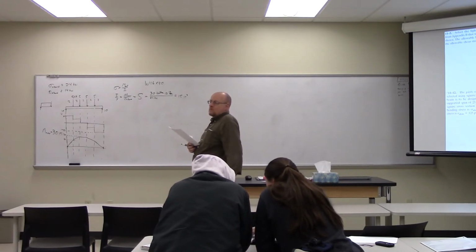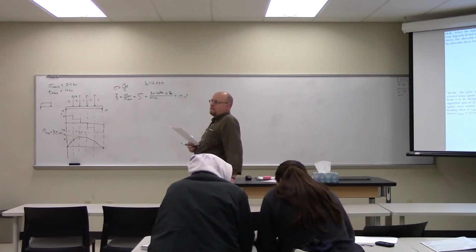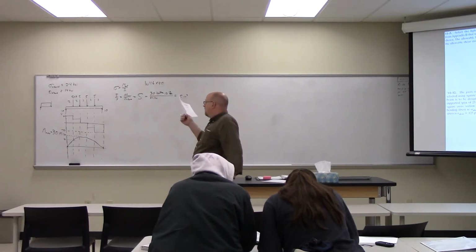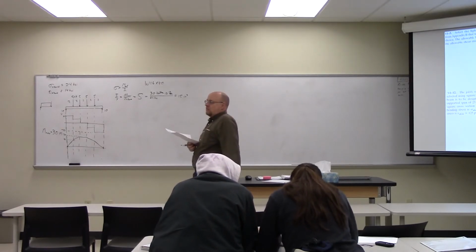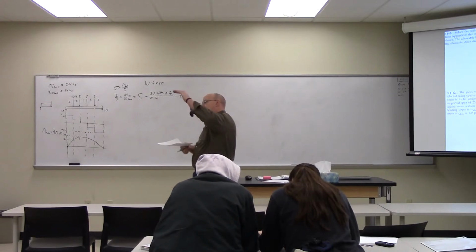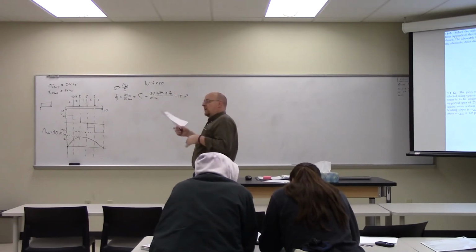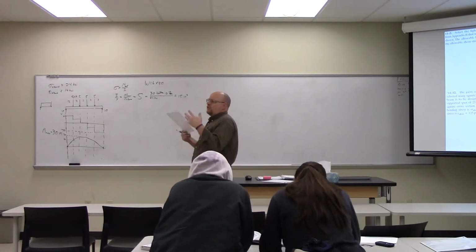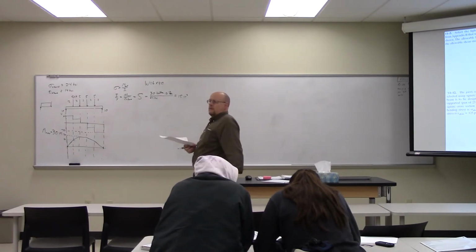Why do they not give the width? They give it in the table, but typically the constraints that we care about are the height. And we'll see about that in a second with the shear, the height, and then we care about the moment of inertia, all those other things too.